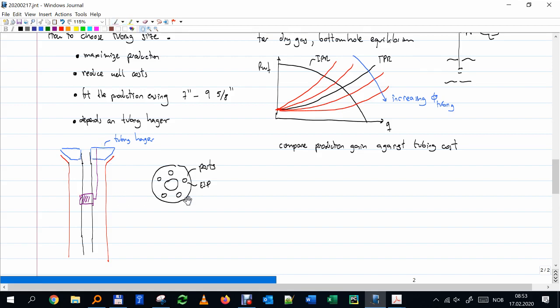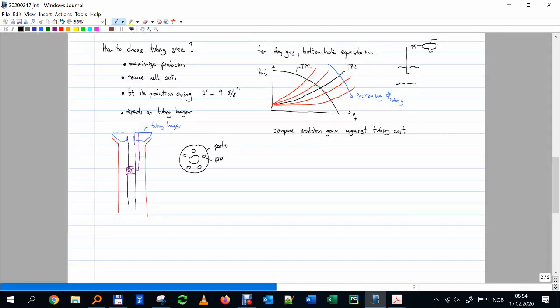that hanger. So if I try to simply make the tubing size bigger and bigger, it might be that due to all the additional things I have to have in the hanger, I cannot go higher than some size, because it will affect the mechanical integrity of the hanger. I cannot put too many holes in this cheese, otherwise it's going to collapse. It won't be able to hold the whole weight of the tubing. More or less because of that.